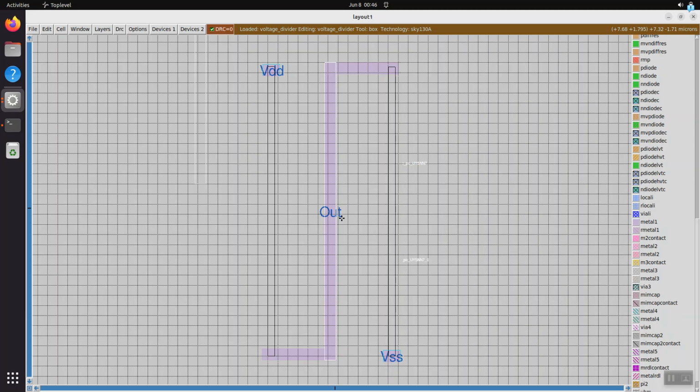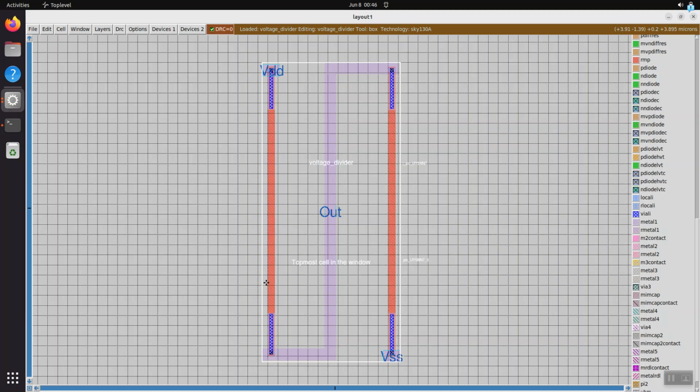Now we should be something. Let me just select that. I'm hovering over here, pressing S until everything is selected, then pressing X, and see no DRC errors. So rather than DRC being a separate step, at least at this level of design, it's happening practically instantaneously. So that's an advantage, because as soon as you see a mistake, it pops up. So in a way, better to learn, I think.